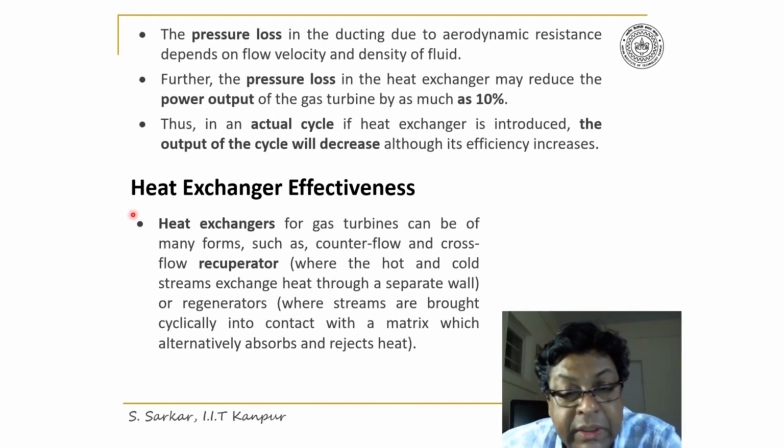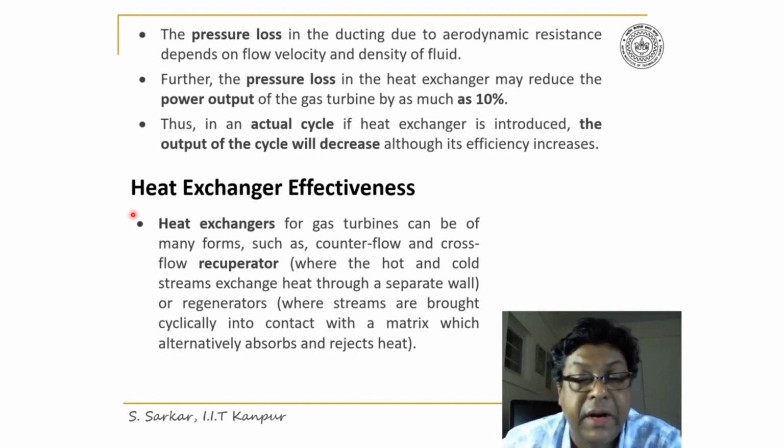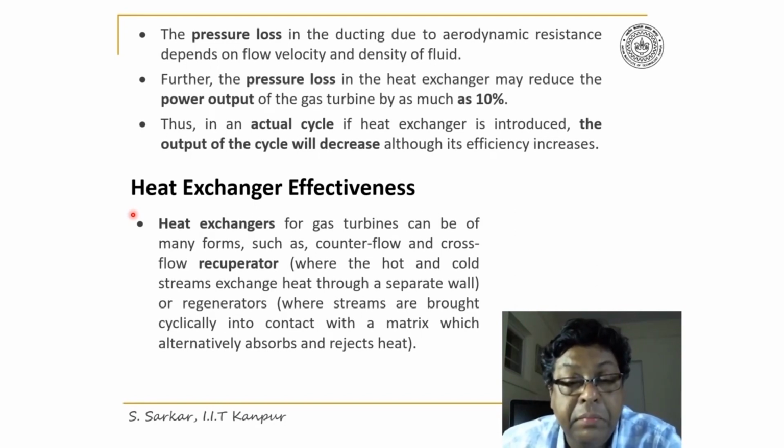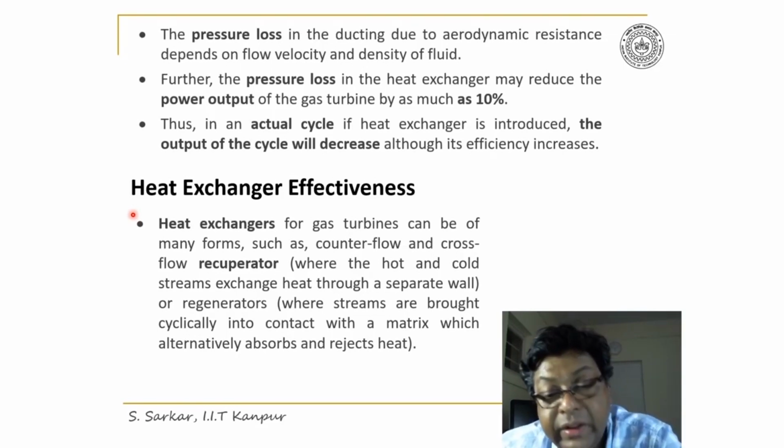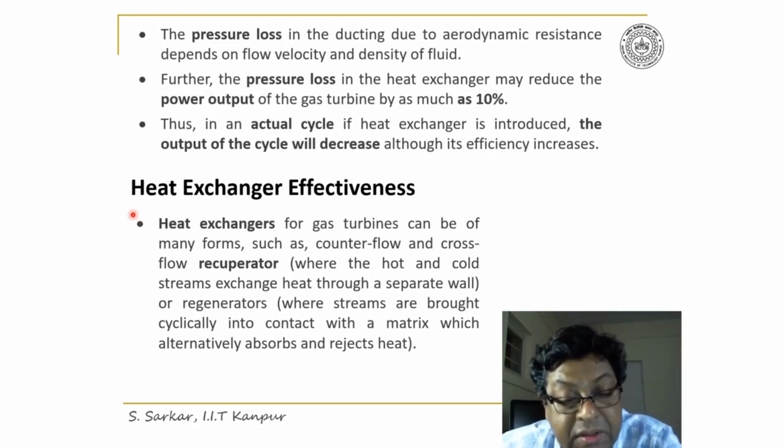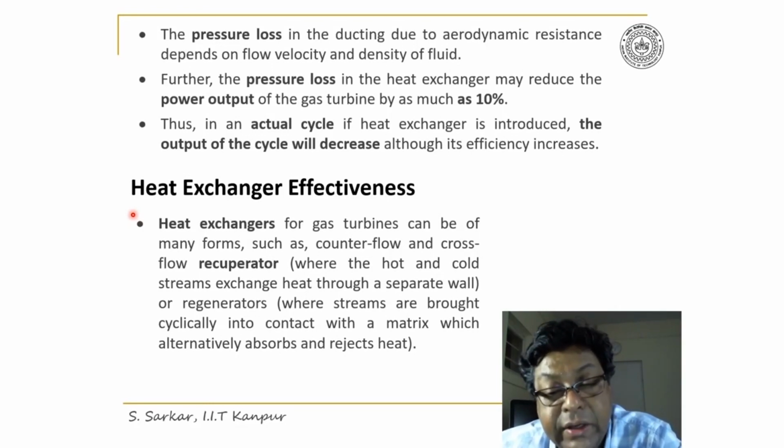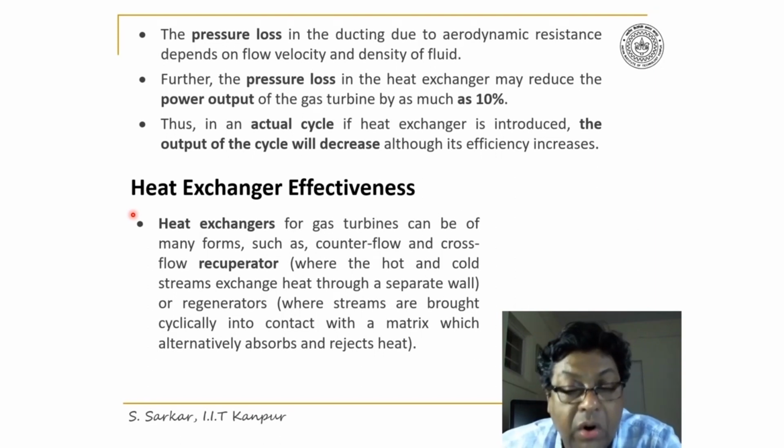Please note that a heat exchanger for a gas turbine can be of many forms, such as the counterflow and crossflow recuperator, where the hot and cold streams exchange heat through a separate wall, or a regenerator, where the streams are brought cyclically into contact with a matrix which alternately absorbs or rejects heat.